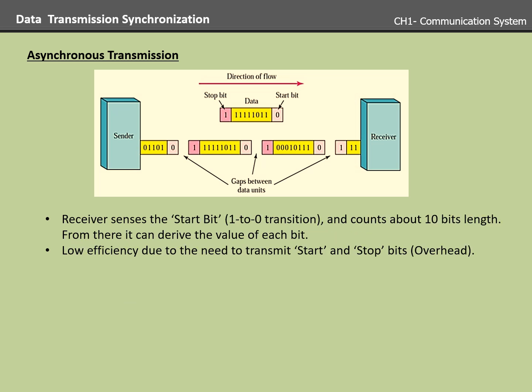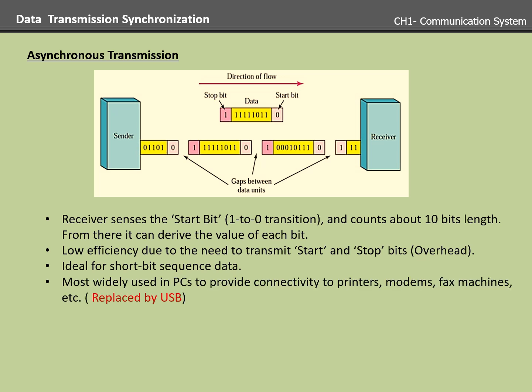For asynchronous transmission, it has low efficiency due to the need of start and stop bits. We call them the overhead. But it is ideal for short bit sequence data transmission. It is mostly used to connect PC to devices, and it has already been replaced by USB.